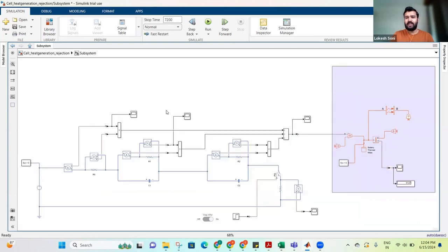One more point here is that it is very lumped mass sort of thing. I am not monitoring what would be the temperature at the center part of the cell, at the top part of the cell, at the bottom part, because I don't have to. For me, all it matters is what is the averaged value, because algorithms anyway take some safety margin. I don't want to be very precise, since it is, let's say, a safety algorithm. Knowing an average value at lumped mass level is okay. I will anyway put a safety margin on it and then have my algorithm in place, right?